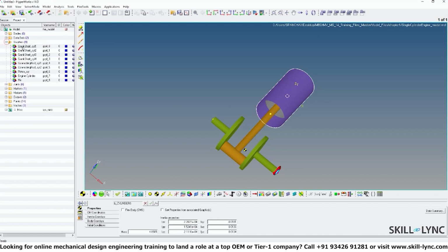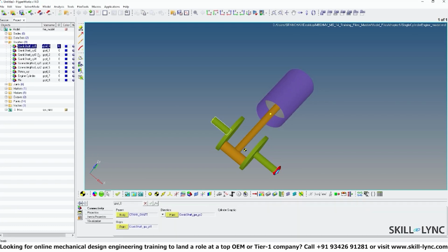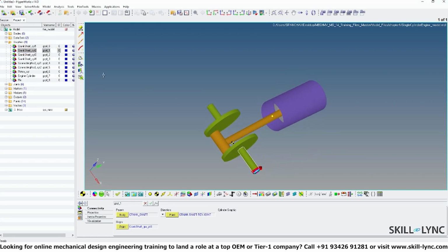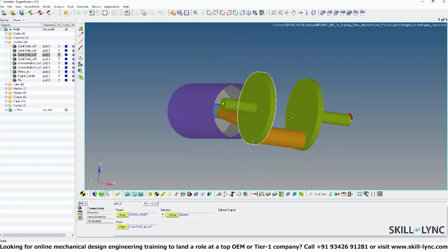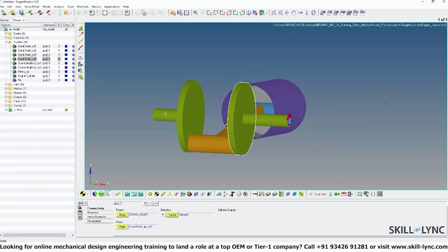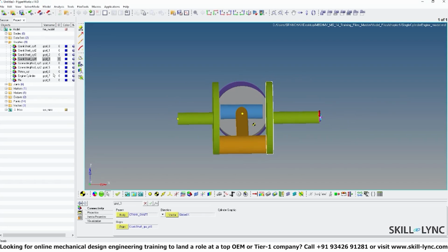And the graphics that we're using, all of these are primitive graphics which are available in MotionView. So we're using a cylinder for the crankshaft, a cylinder again here. This highlighted part that you can see is also part of the crankshaft, which is modeled using a cylinder. Same thing even here. So the whole crankshaft is modeled using 4 cylinders. Cylinder 1, 2, 3, 4.